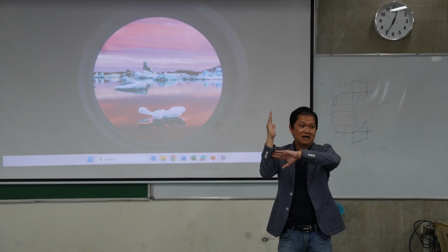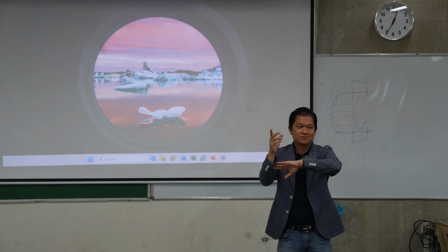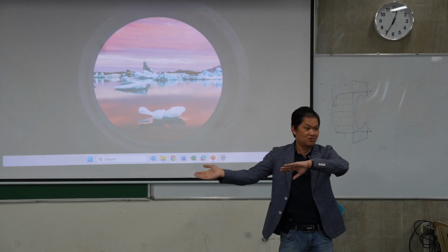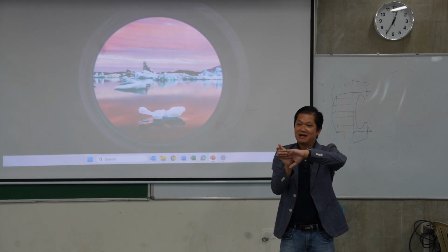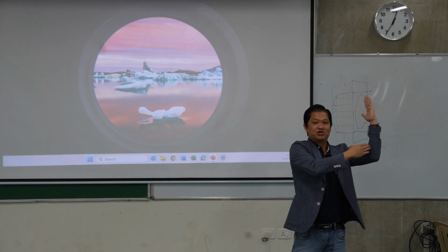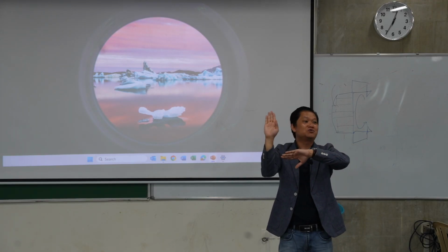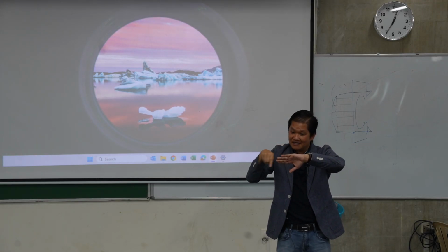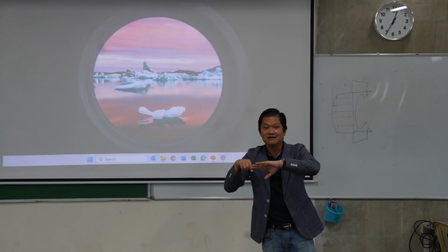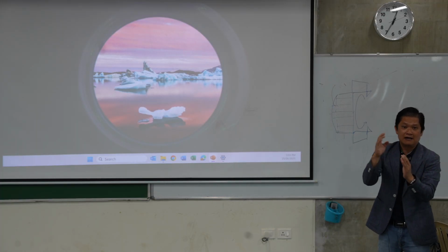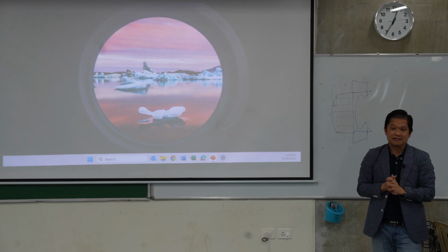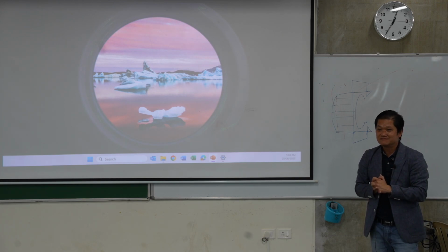But when you have a high-rise building with high load, wind load blows in here, so that actually pushes on our member, and that member goes into the shear core. So there is actually a huge compression as well. So then we need to look at the interaction here to see the effect of the combined action, compression and shear. Okay.